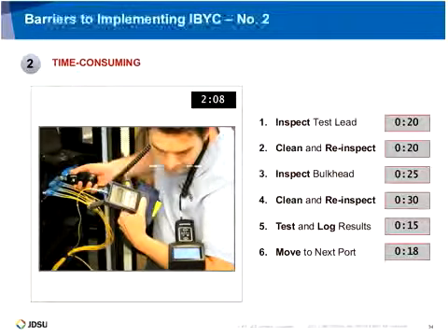But now we're at a point where it's no longer just a best practice. Now this is something that's included in 568C. And I've actually talked to a handful of design engineers now who, when they're writing their job requirements, are fed up with the issues they've been dealing with, connectors being contaminated and impacting the job performance.